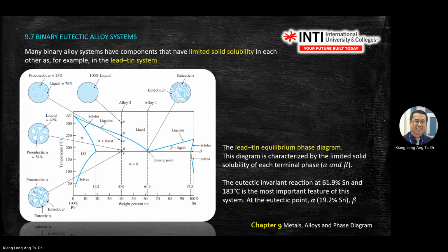And then also, it will ask you to find at what percentage of that component. So you draw to the eutectic, you reach the intersection point, then you draw one line and read the reading from the bottom, in this case about 62%. So here you have 61%, 62% Sn, and at the eutectic point you have two solids.